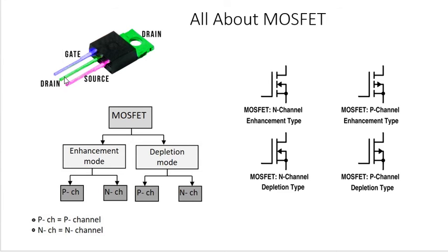You can see the drain color, we have provided it as green and its body is also green. Sorry, the body metallic part is green. So it means that the body is at drain potential and it is internally connected. So in case you are using MOSFETs in parallel on a heatsink, you can simply place these MOSFETs on the heatsink and tie them down, and you need not connect their drain terminals together. On the PCB you only have to make a path for the source terminal.